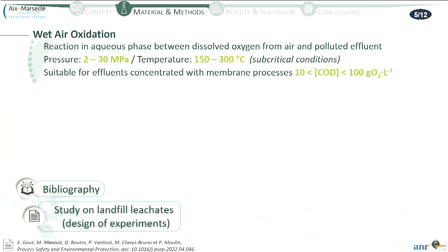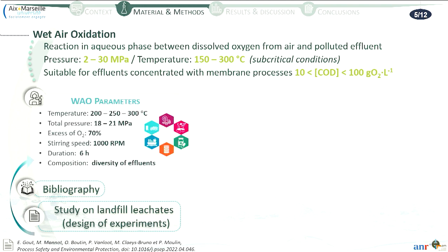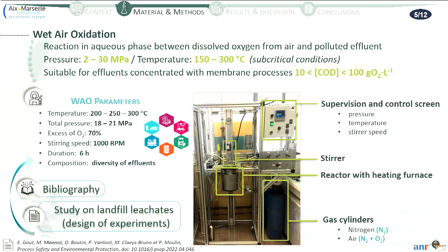So we first studied landfill leachates, and with the use of bibliography, we wanted to work on different temperatures and pressures. And we used a lab-scale reactor that is composed of a supervision screen for temperature, pressure, and stir speed. The reaction occurred in a reactor with a heating furnace, and we had 2 gas cylinders with or without oxygen.